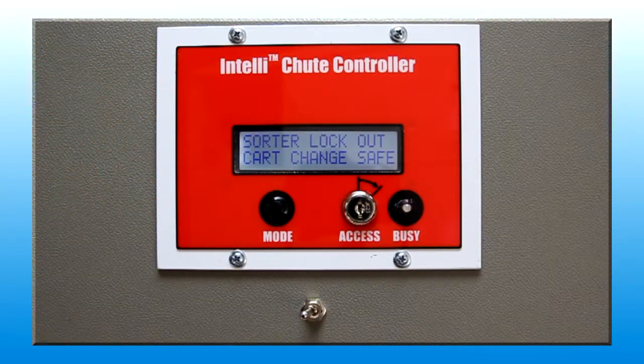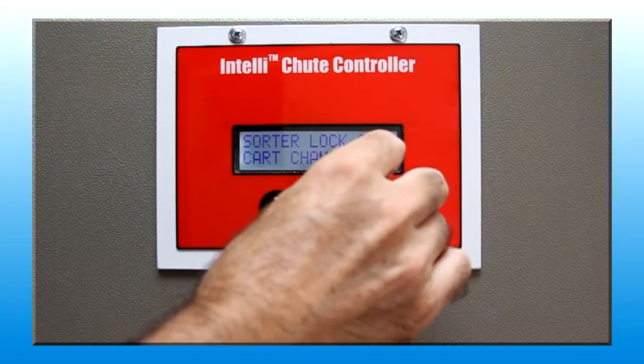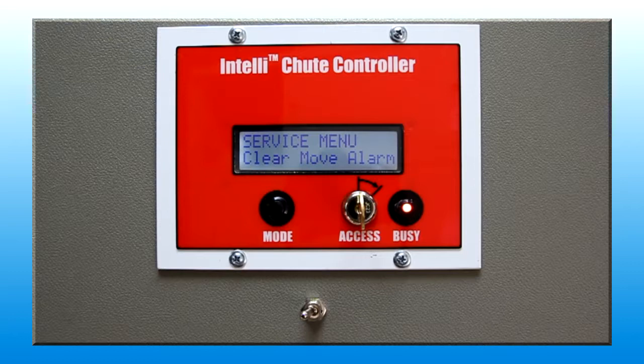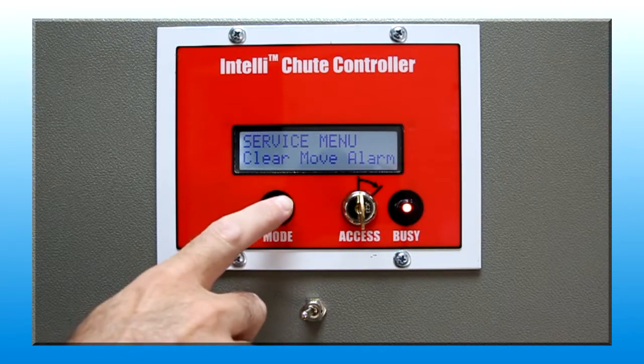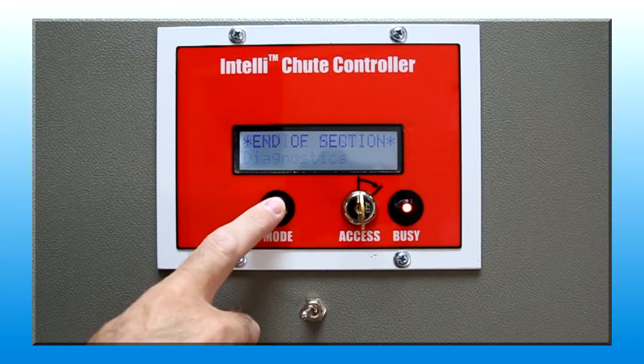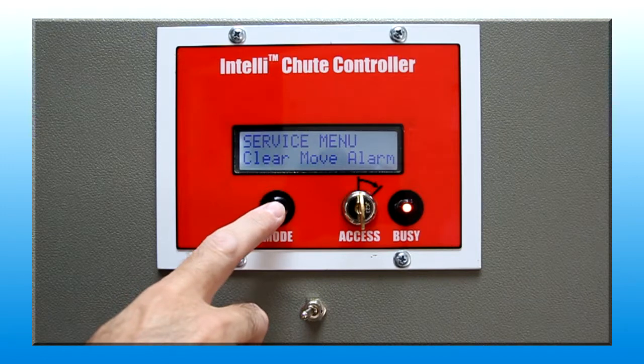Lockout mode in conjunction with a keyed access switch also provides access to the control system service menu area of the operating system. The service menu contains multiple sub-menu items. Press and release the mode button to navigate through the list. An end of section marker follows the last item, and pressing the mode button loops around to the beginning of the list.